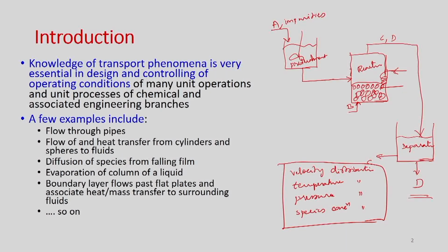In these kinds of cases, you also need to have some information like friction factor, drag coefficient, Nusselt number, Sherwood number, etc. These things are also important, which are in general again related to the velocity distributions or temperature distributions or species concentration distributions. They may also depend on the properties of the material, they may also depend on the geometry of these things, all these things. All this accurate information, in general, it is very difficult to get from a coursework, because very complex phenomena may occur.